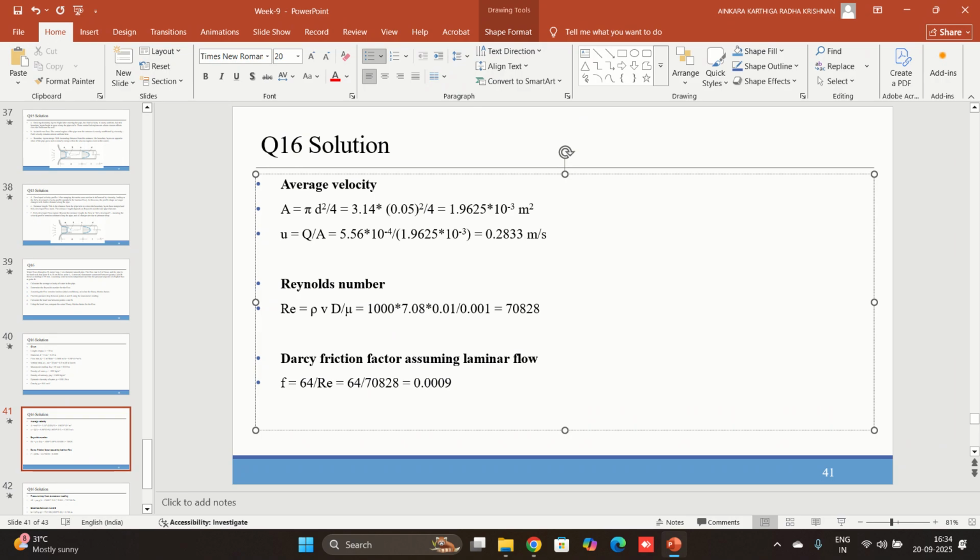Previously our diameter was low, but flow rate was the same. So since the diameter was small and with the high flow rate, we had a high velocity. But now the same flow rate was maintained, but our diameter was increased, so the velocity also decreased. Previously diameter was small, so to have that much flow rate in that small area, we had the higher velocity. But now since our pipe diameter is larger, velocity decreased. So that is the thing.